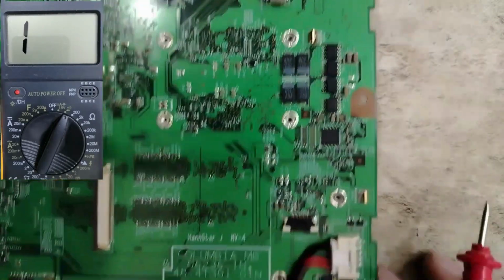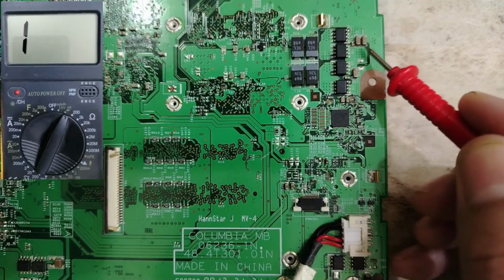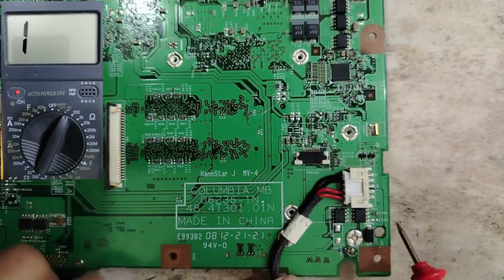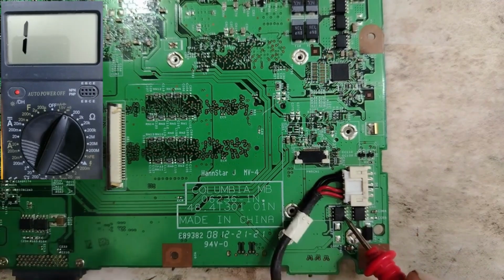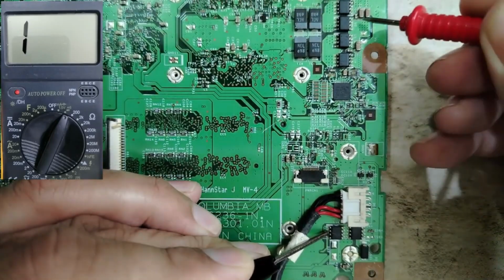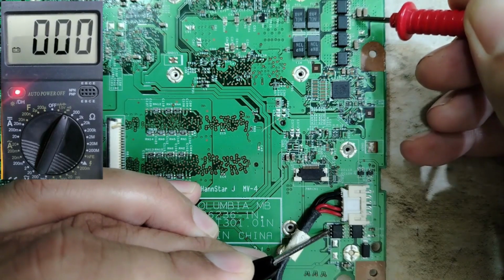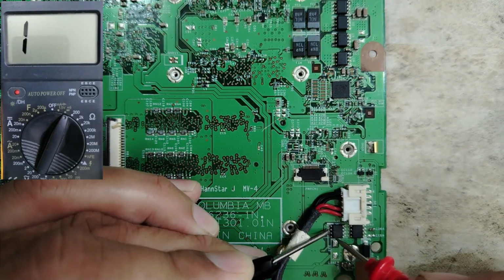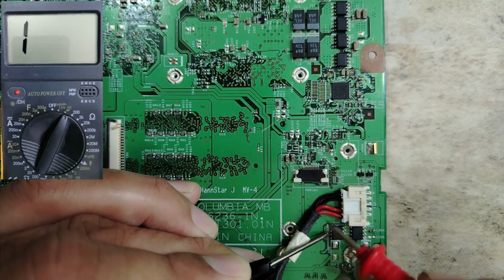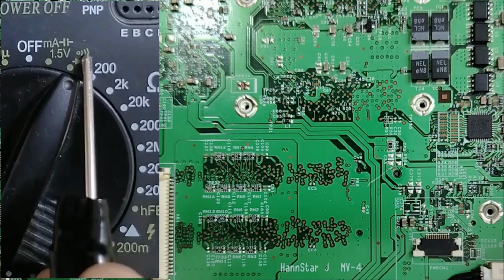So let's zoom out a little bit. So here we have the CPU circuit. Let's check if these ceramic capacitors are the input or not. So here we have the input. Do you see the power jack? As you can see here we have the first switch, the second switch. So if we check between this switch here, okay, and these ceramic capacitors, we get, as you see in the multimeter, very low resistance, and of course we get continuity. Means this switch is connected directly to the ceramic capacitors. Means here we have 19 volt, it will pass directly to this side. Of course, we select here the buzzer or the continuity option.